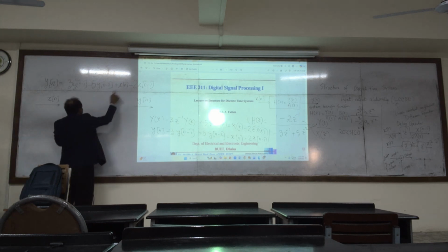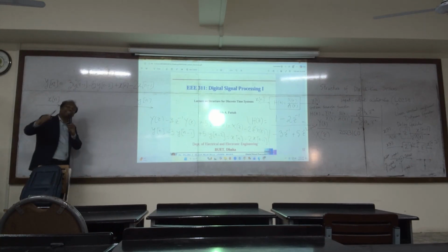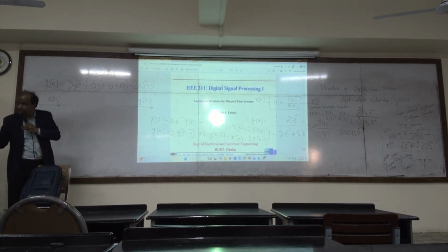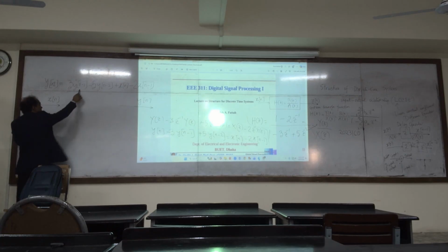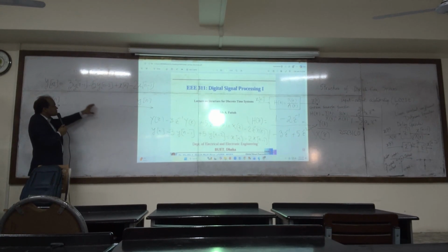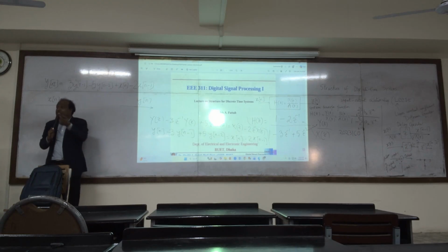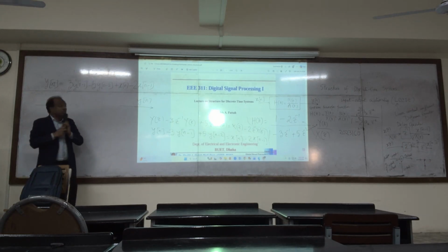You need x(n). Okay, fine, x(n) is here, so I can get x(n) from here. But I need y(n minus 1). How to obtain y(n minus 1) here? We have z inverse, which means you need a delay element.